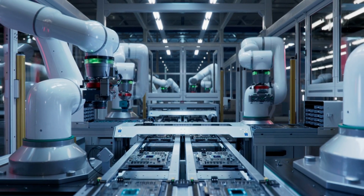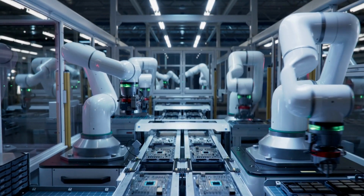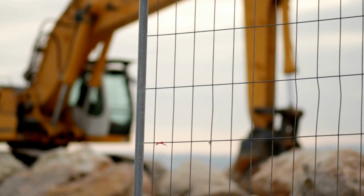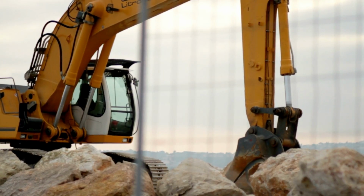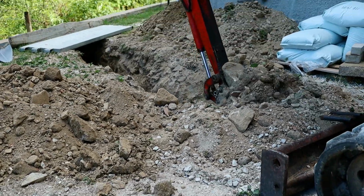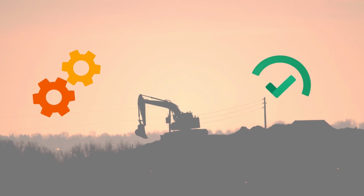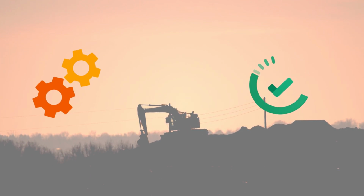The most important point is that this automation does not rely on complex robot behavior. The system does not try to calculate perfect joint positions. It simply observes where the bucket actually is and reacts to that position. Because of this, the automation remains reliable even when loads change, structures flex, and hydraulic behavior is not ideal.